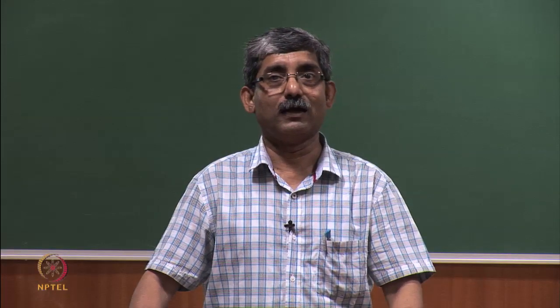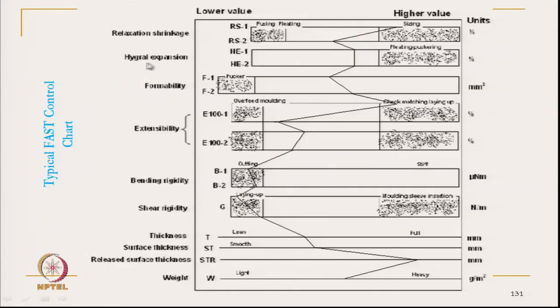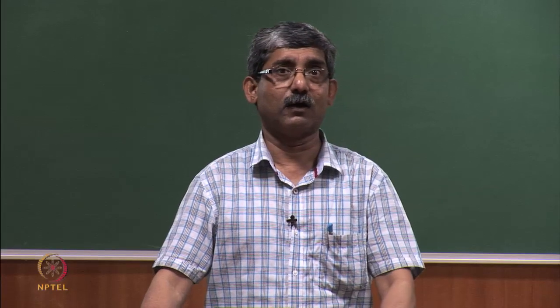Okay. And say hygral expansion, it is perfect, warp wise and weft wise hygral expansion is exactly the same. Here warp wise and weft wise there is a wide difference. Similarly, we can see this fabric will have a check matching problem, at least in the warp direction. So, it has lower bending rigidity, it has a problem with this. So, this will give an idea of the potential problem which it is going to have. So, we can take precaution.